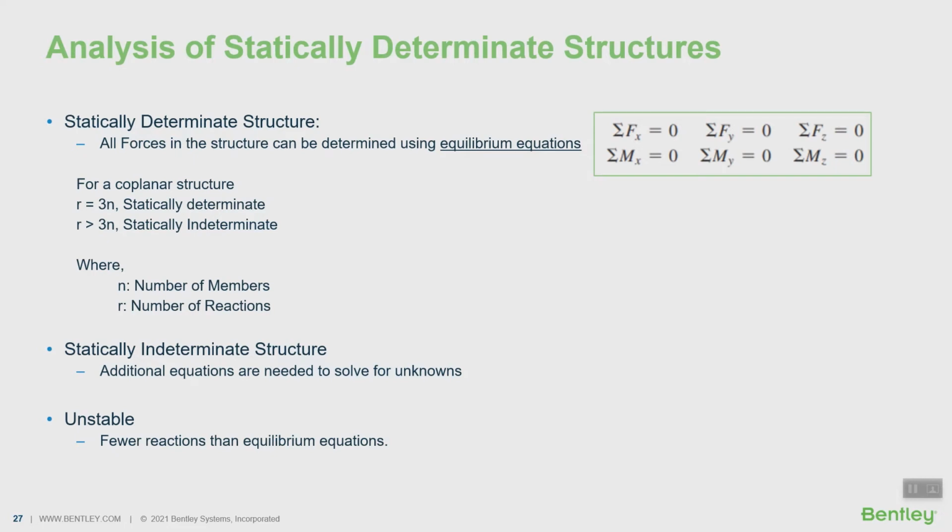After we have an idealized model, we need to find out the determinacy of the structure so that we can choose the right method for analysis. Whether the idealized structural model is statically determinate or not can be determined based on the number of members and reactions. The forces in a determinate system can be found completely by solving the equilibrium equations, whereas for an indeterminate structure, we would be required to solve additional equations to get all the forces.